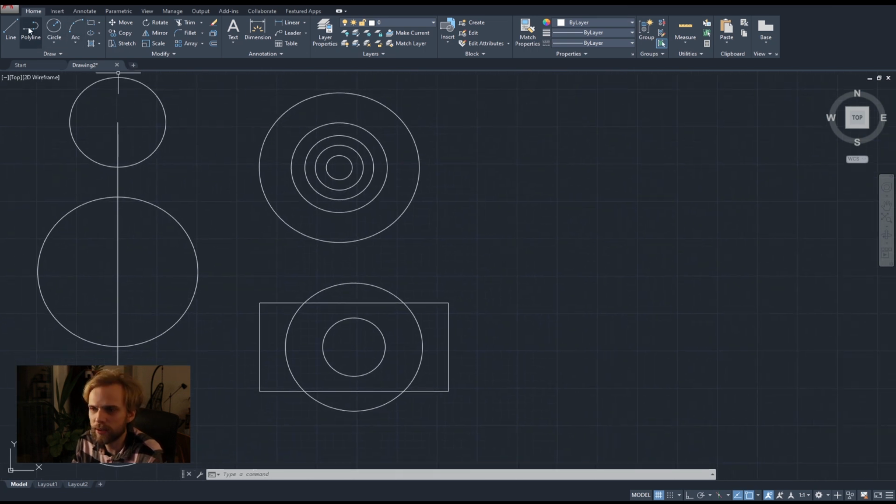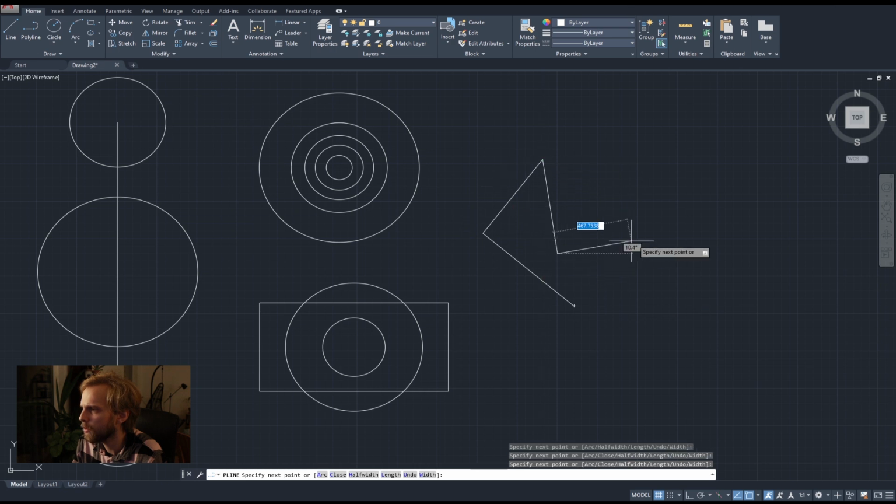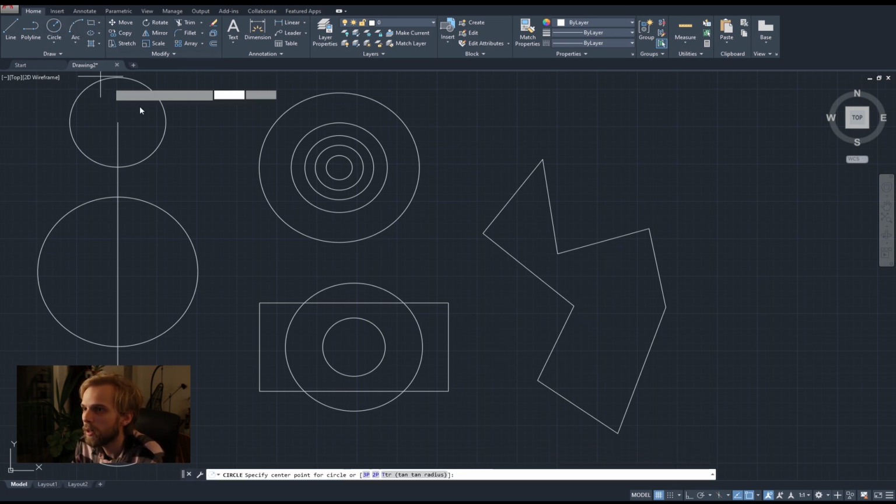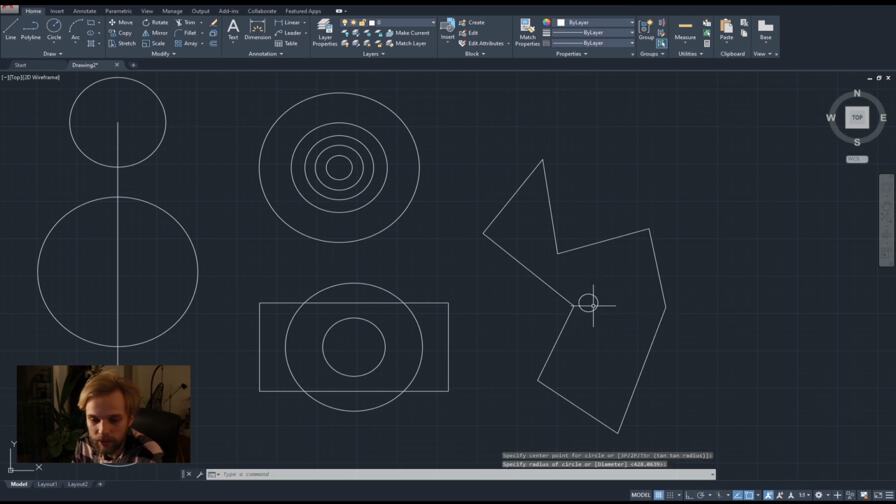There's more stuff that you can do. For instance, if you have a polyline which makes a weird form, something like that, and as long as that polyline is closed, meaning it needs to end where it started, click, and then hit enter, right? It's a closed polyline right now. And I grab a circle, it will show me where the geometric centroid is, right? And I can snap to it, but it's of course going to be funky. It is accurate, mathematically it is an accurate geometric centroid of this particular shape, but it might be counterintuitive for you visually, right?